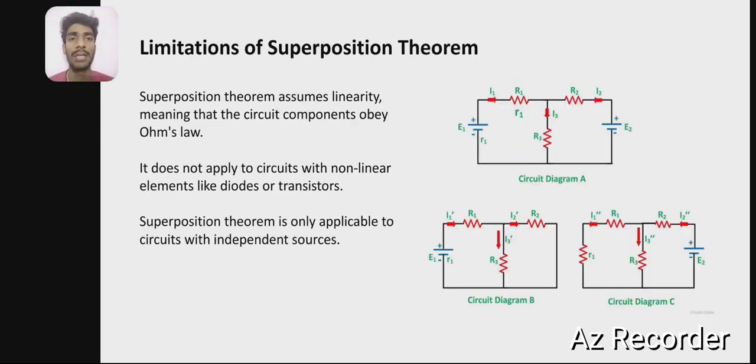Limitations of superposition theorem. Superposition theorem assumes linearity, meaning that the circuit components obey Ohm's law. It does not apply to circuits with non-linear elements like diodes or transistors. Superposition theorem is only applicable to circuits with independent sources.